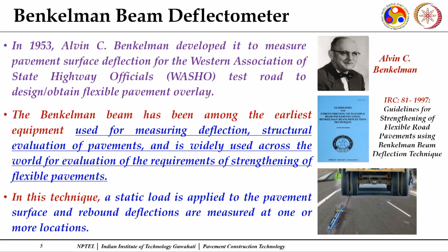Today in this lecture, we will discuss the Benkelman beam deflection technique for structural evaluation of flexible pavements. In 1953, Alvin C. Benkelman developed the Benkelman beam to measure pavement surface deflection, specifically for the Western Association of State Highway Officials test road, to obtain the design of flexible pavement overlay. Thereafter, continuous research and many exercises across the globe have been done on working out Benkelman beam deflections to determine the overlay thickness for strengthening of flexible pavements.